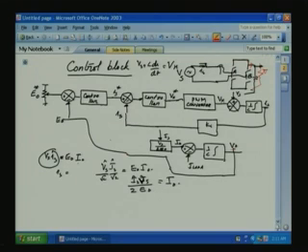So, with a sudden change in load, the difference will immediately go through this one and there will be a change in the capacitor voltage V0. That difference in current at the moment of sudden change in load, I0 minus IL, integral 1 by C integral of this difference, we will feed back to this one here. Okay. Now, the moment the change happens, immediately IS has to change.